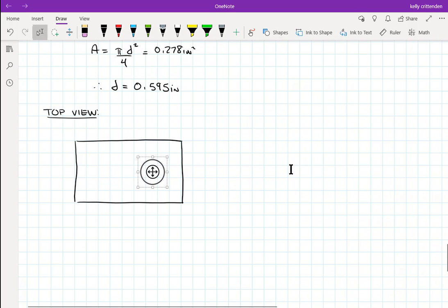All right, let's say that we have a plate. It's got a hole in it again. There's a bolt in there or a pin or whatever, and we're still pulling on it this way. And let's say that we made the bolt super strong, and the bolt is not our problem. Then we run into maybe the bearing stress being a problem. It deforms the hole to where it's oblong, egg-shaped, and that's a problem.